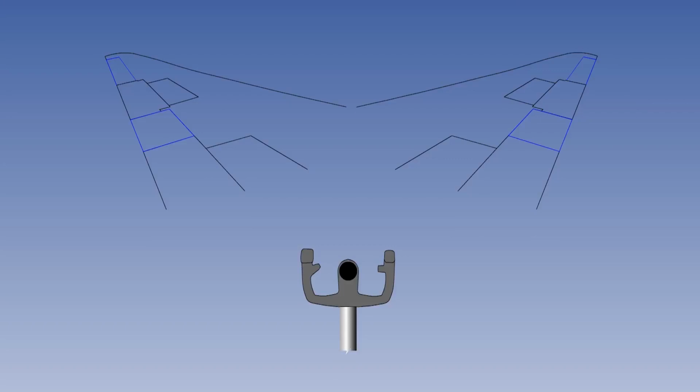You have previously been shown that flaps are fitted to the trailing edge of the wing, and you have now been shown that ailerons also occupy part of the wing trailing edge. The resulting reduction in flap area reduces the efficiency of the flaps. On large, modern, high-speed jet transport aircraft, this reduction in flap area is a significant disadvantage, so design changes have been made to make the ailerons also work as flaps. Hence the name flaperons.